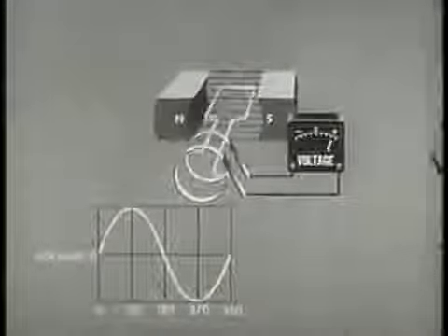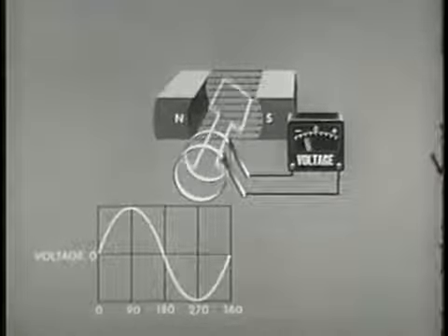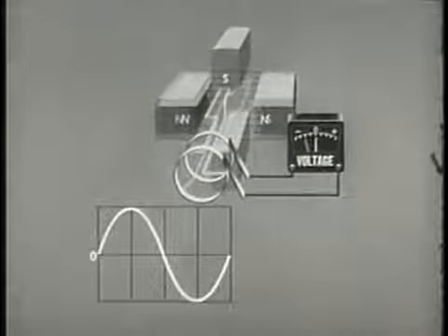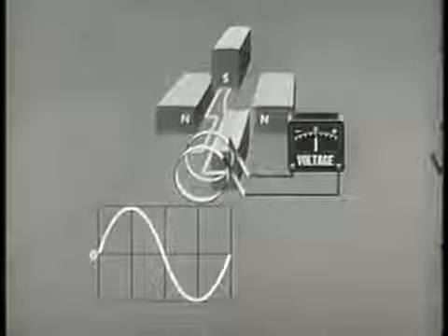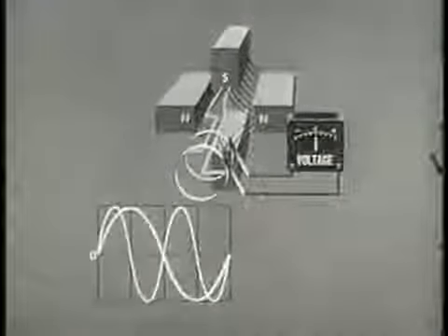In this example, the two-pole machine used has one magnetic field. As the armature makes one revolution, one magnetic field is traversed. Adding another pair of poles adds another magnetic field. Now there are two magnetic fields. The armature moves through one field in half a revolution. In one complete revolution of 360 mechanical